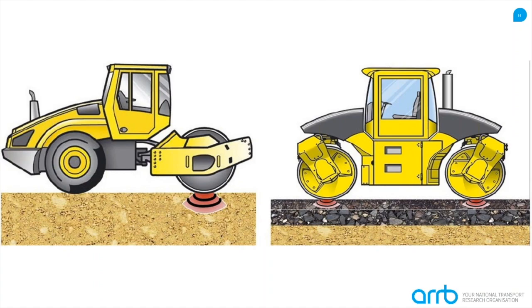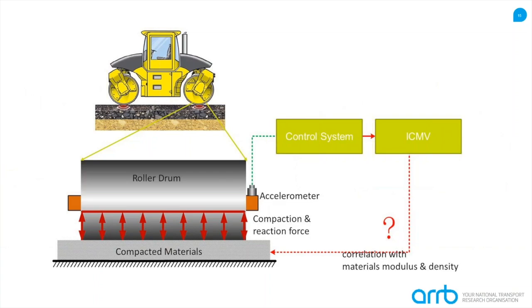When IC was invented about 1978, for the next 20 years, IC, or CCC, continuous compaction control, was normally used for the single drum roller for soil and sub-base compaction. IC has only started to be used for asphalt compaction in the last 20 years. The slow development is because a lot of models have to be simplified in order to build into the IC roller to measure the stiffness of the material.